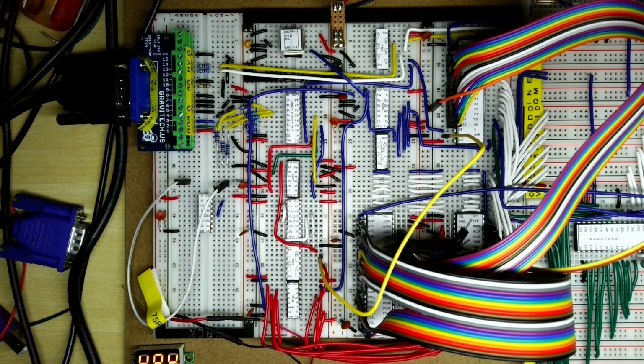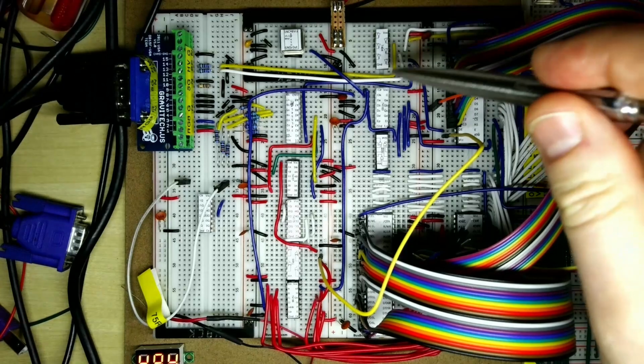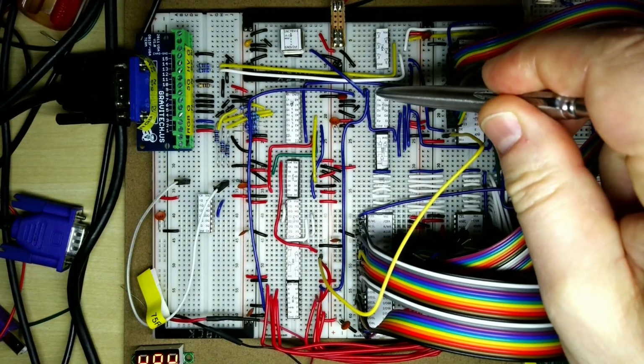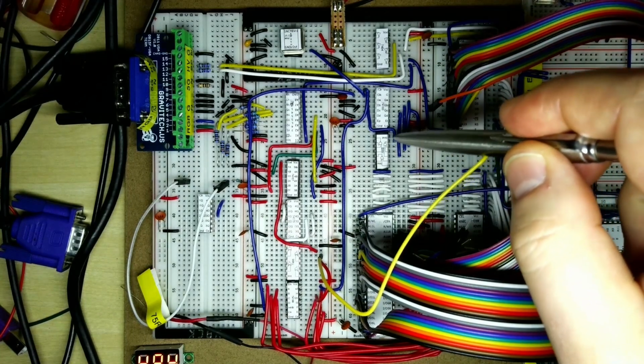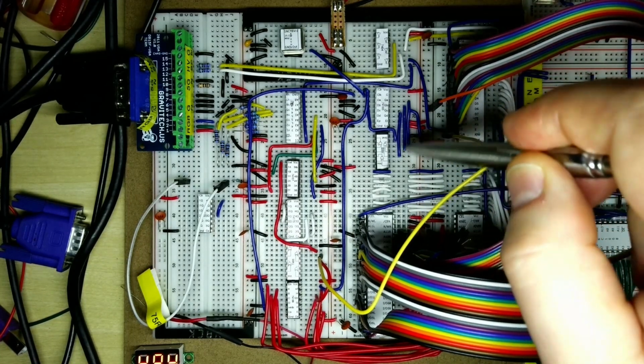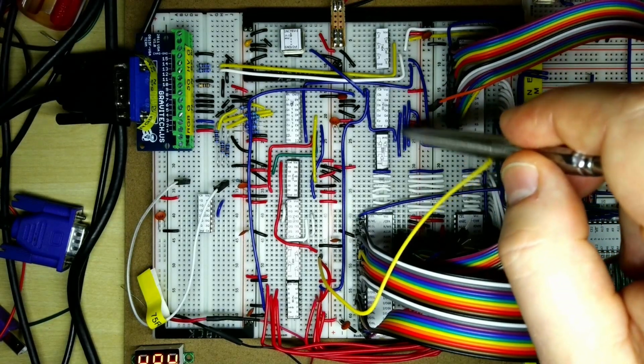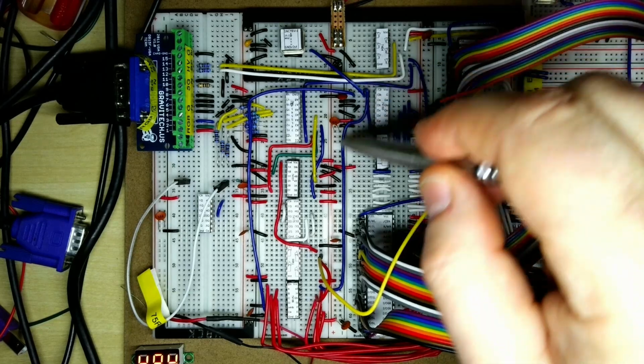So the next thing we're going to do is to look at the timing for the loading of the shift register. So the loading of the shift register is by this pin here at the top, down as SL, shift load, and at the moment this is coming from the signal at the top here, which is the clear signal for the counter here, and the signal for that is in fact coming out for when the QA, QB, QC are all 1, then that produces a low signal here. So that's the signal that we're currently using.